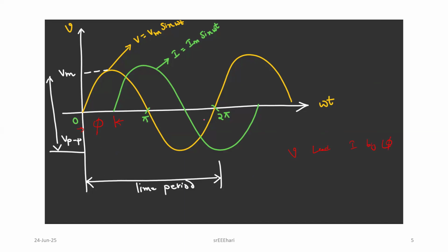One complete cycle, that is, one positive half and one negative half, is called the time period. When I know the time period, frequency is nothing but its reciprocal. The maximum value is Vm or peak value Vp. From the maximum positive peak to the negative peak is called the peak to peak voltage. These are simple definitions from the sinusoidal waveform.